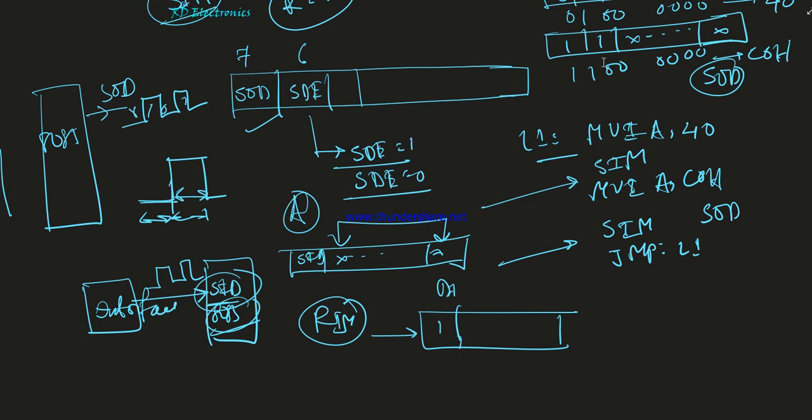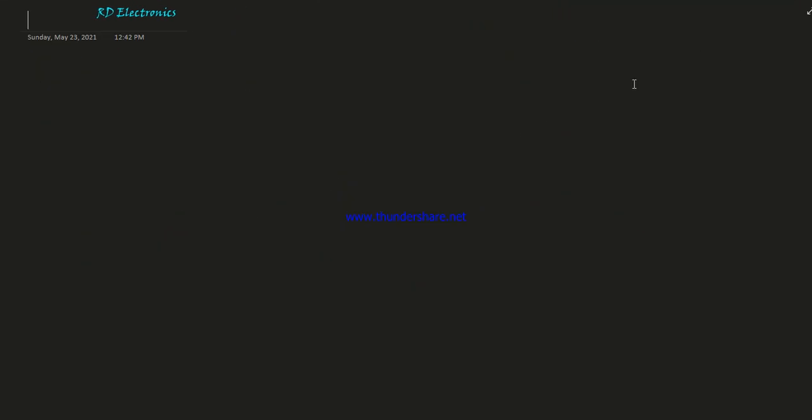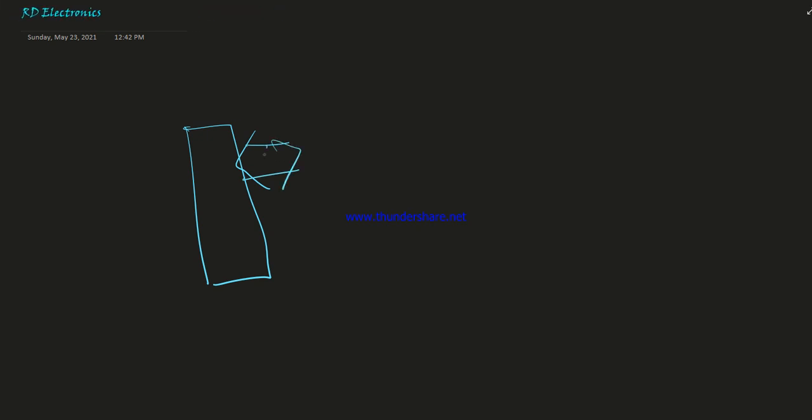We already know that the 8085 has 8 data bus lines available, connected to the peripheral. So these 8 data lines mean 8 parallel wires from the 8085 to any peripheral device. That increases the hardware complexity too much. To avoid this, we can just use serial data transfer. Only one serial data line can be used to transfer data between the microprocessor and the peripheral device.